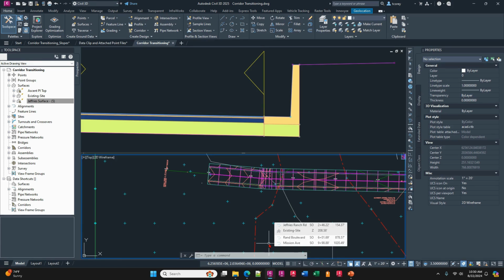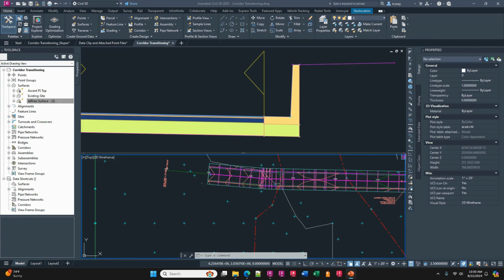Should I set index control in every drawing or only in those that become Xrefs? Yes, that's a good question. You want to set index control in the drawings that are going to become Xrefs. It does no good to do that in a sheet drawing where your production drawings have been Xref'd in. You don't need to set it there, just in the production drawings themselves.